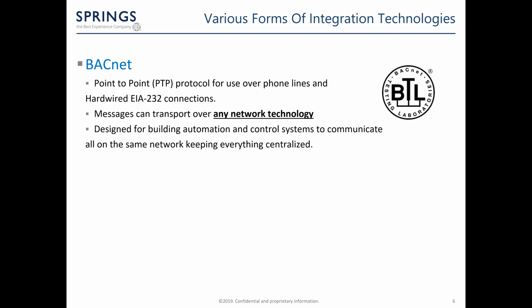The final form of technology integration I'll be sharing with you is BACnet technology. BACnet also defines a dial-up or point-to-point protocol called PTP over phone lines or hardwired EIA-232 connections. The key feature of this technology is that BACnet messages can, in principle, be transported by any network technology.